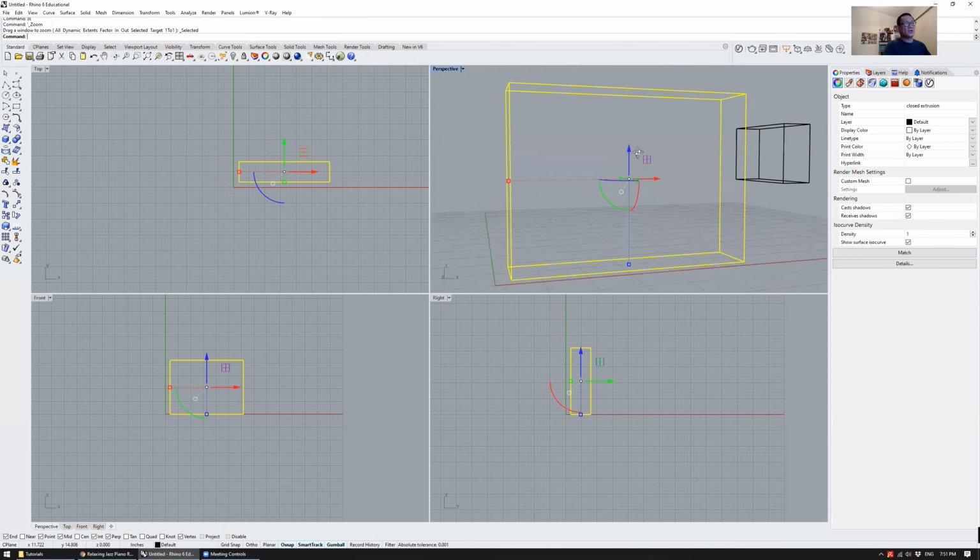Now again, let's go back to tools options. There are a couple of options here I want to set for you, particularly underneath modeling aids. Just to double check, generally this is what yours looks like. In particular, I want to go to Smart Tracking Guides and enable Smart Tracking Guides. Smart Ortho, Smart Tangents and Perpendiculars, Semi-Permanent Points, these should be on. If you go to Cursor Tooltips, turn on Osnap Distance Point. The only one that's not on is the command prompt. So just make sure to set your Rhino settings to these as well.